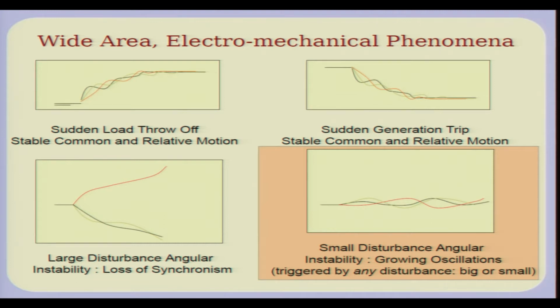Now, remember that eventually in a synchronous grid there is only one frequency in steady state if you are stable. If you are stable, all machines are in synchronism, and if they are in synchronism, that means the frequency everywhere is the same. The governors effectively are trying to regulate the frequency, but there are many governors and many generators, and they are locally trying to regulate the frequency. Now, the question then arises is how do these generators share their responsibility of regulating the frequency.